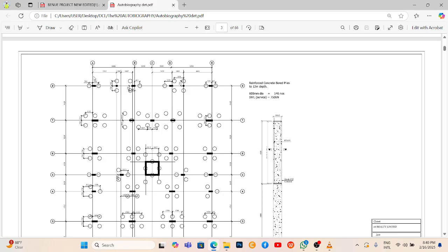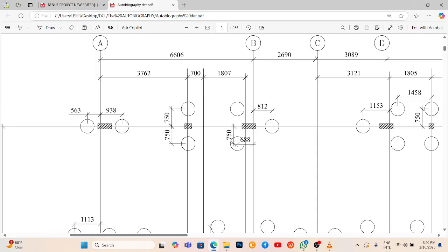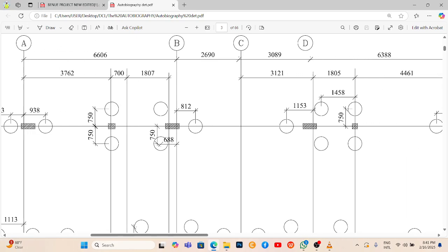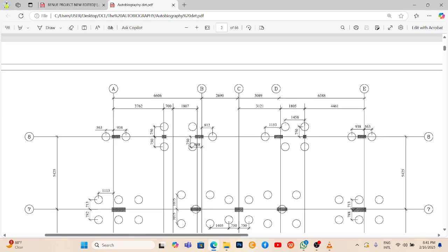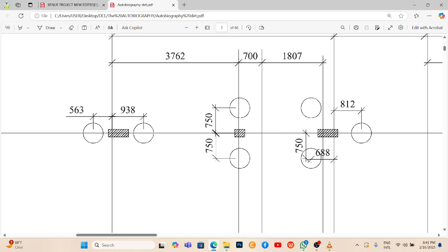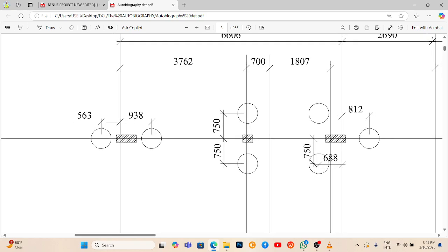You can see from this structural drawing, we have some places that have circles. Those are the ones that indicate the pile positions. There are dimensions that connect those circles, or let me say a reference from the grid line that you can always use to check the circle, to check the pile position. And in between you see a rectangle shape. That's a column, of different shape rather.